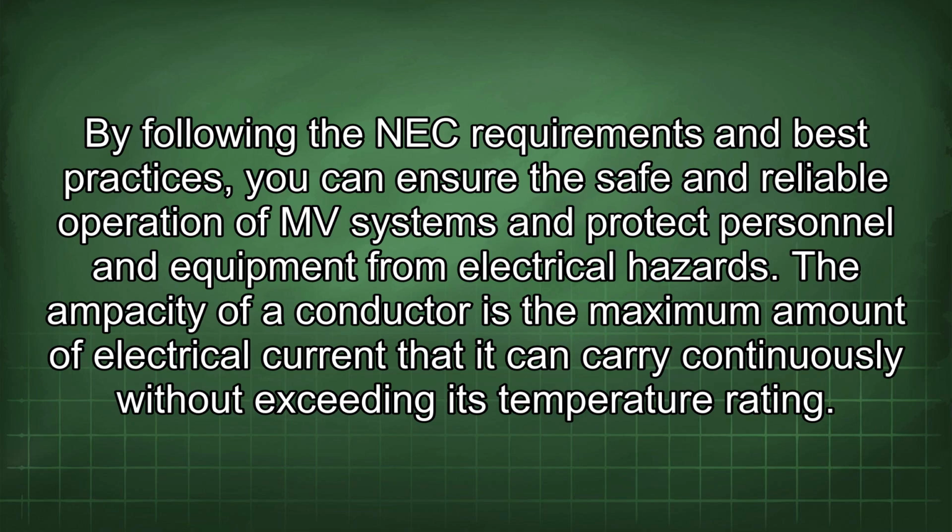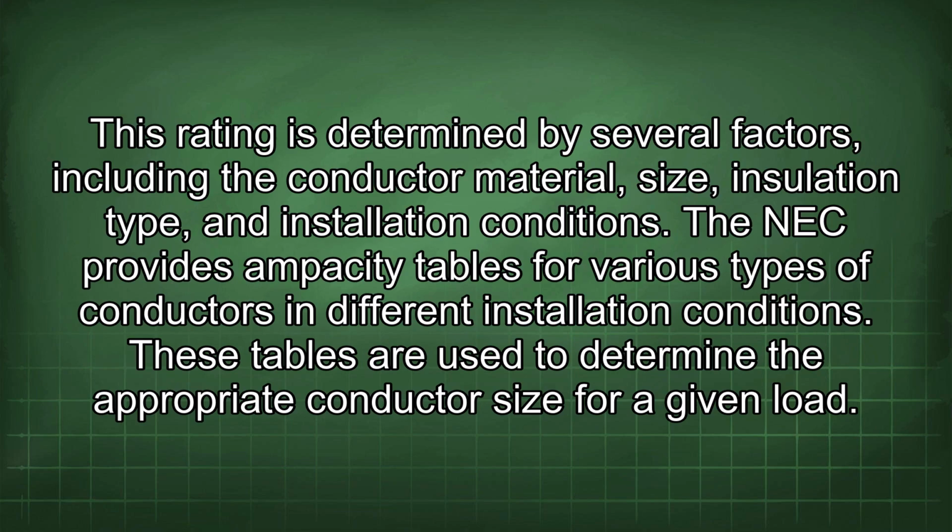The ampacity of a conductor is the maximum amount of electrical current that it can carry continuously without exceeding its temperature rating. This rating is determined by several factors, including the conductor material, size, insulation type, and installation conditions. The NEC provides ampacity tables for various types of conductors in different installation conditions. These tables are used to determine the appropriate conductor size for a given load.